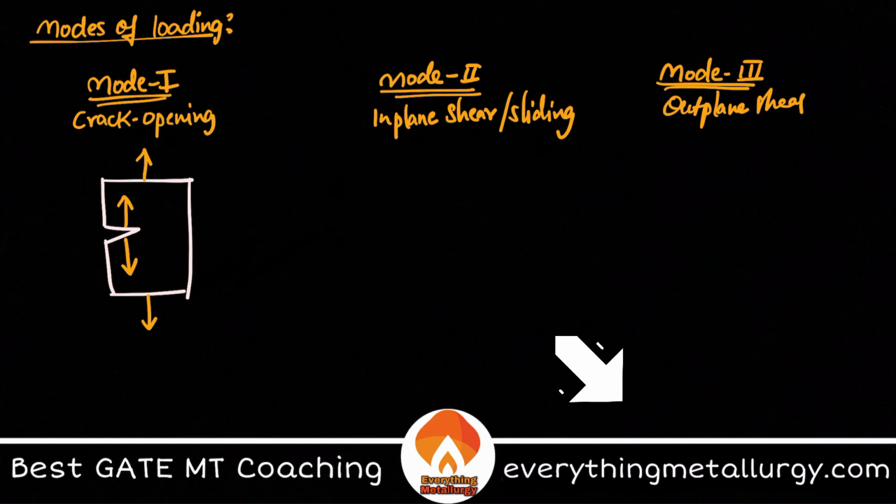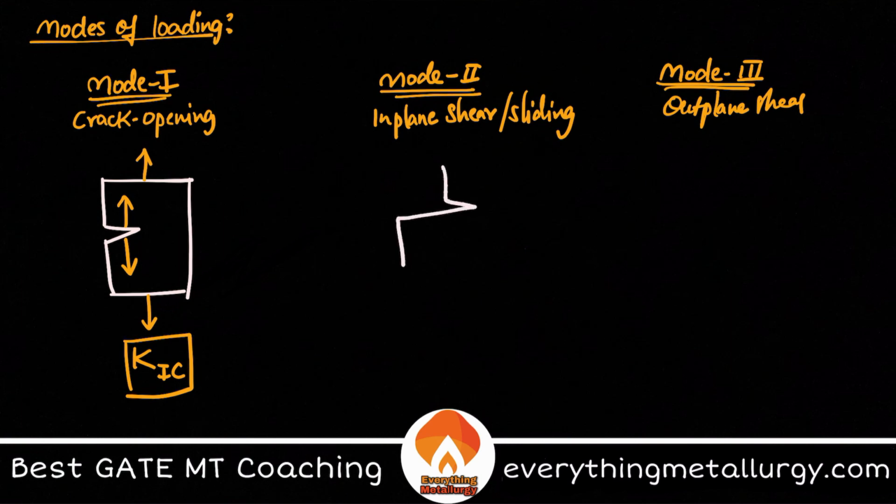So that's why it is called mode 1 or crack opening mode. So the fracture toughness which we get from this mode of loading can be taken as KIC. Similarly, in-plane mode will look something like this.